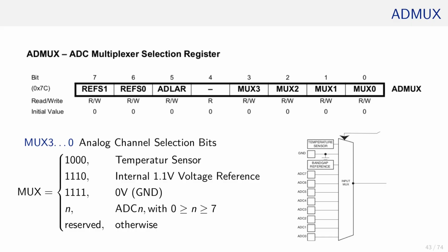As a note from experience, if you would like to read from multiple channels consecutively and change channels after one sample process is over to start the next one with a different channel, it is advisable to discard the first reading from the new channel. There might be a charge left on this wire which needs to be discharged first. Therefore, to have a more accurate reading, either wait some time or discard the first reading.